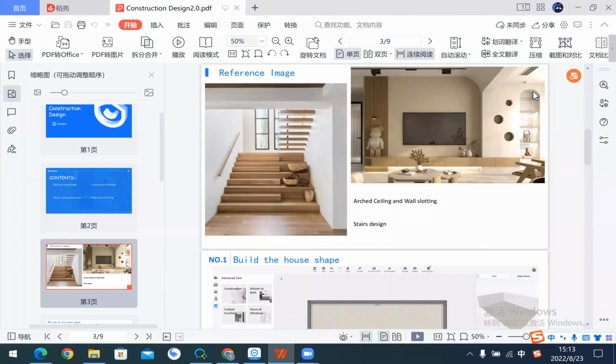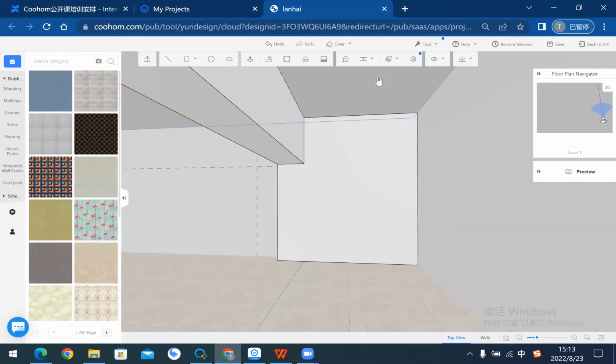And they also have a shape like this. We can understand this shape: we can draw a rectangular and draw an egg. We do the same, just add the guides to make sure this shape's position is maybe 150 to the edge, and its width is equal to 700.